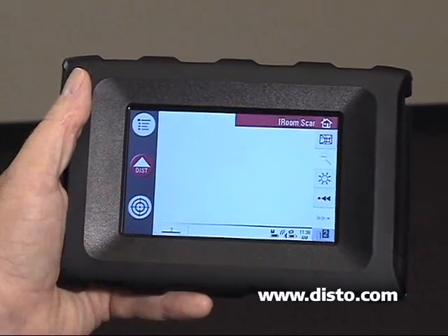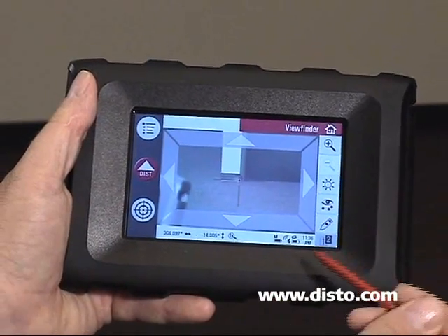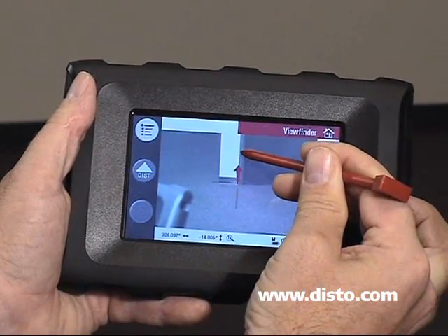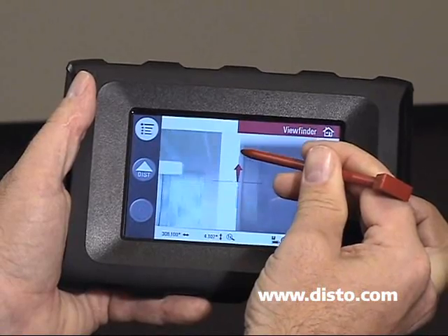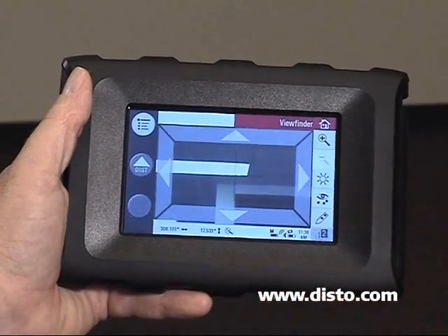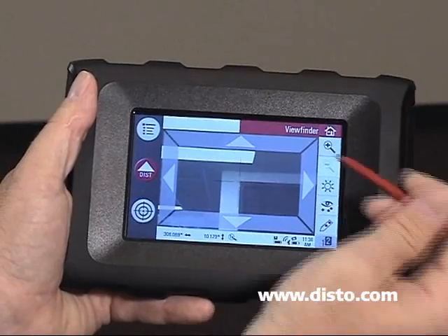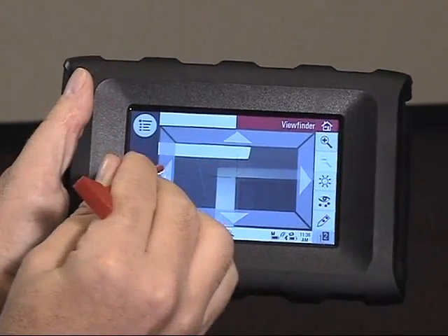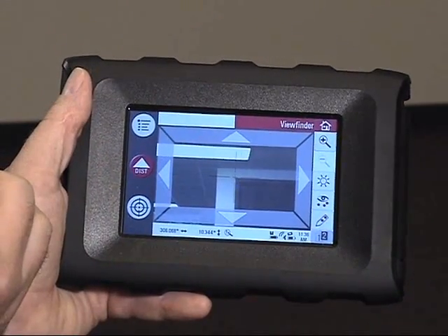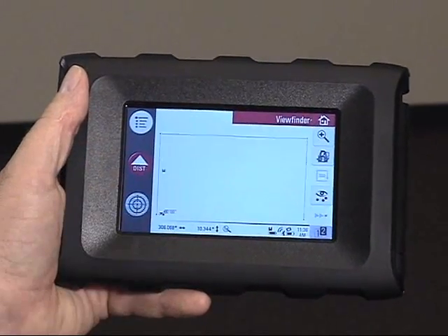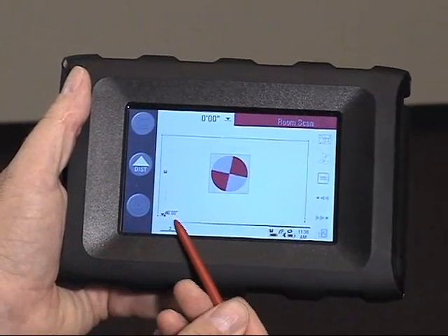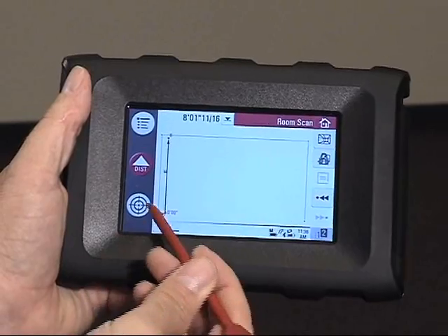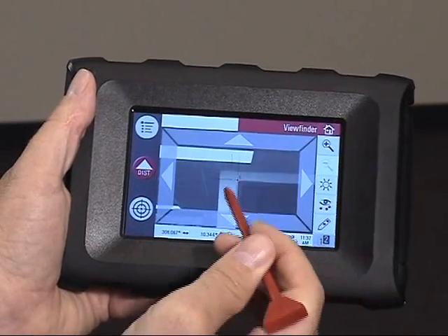Now let's go ahead and do the balance of the door. We're now going to drive the unit up. A little high. Let's drop it back down by tapping on the screen. I can visually look up and see a couple little taps with the fine-tuning arrow keys. I'm up at the top corner of the door. Let's take that shot. Now you'll see we're going to get our vertical line segment representing the left-hand side of the door. Activate the view screen again.